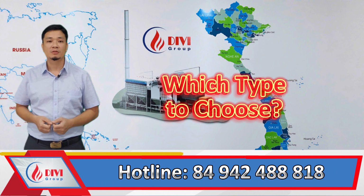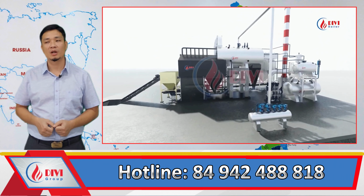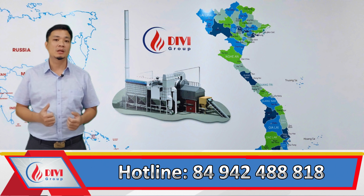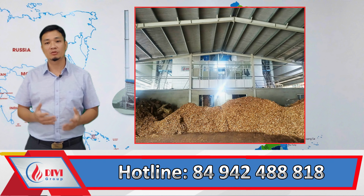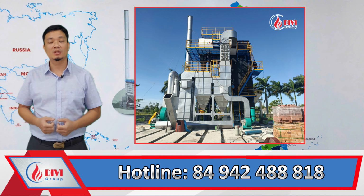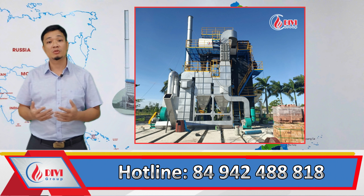When to choose which? If there are no specific site constraints, the CFB design is generally preferred. However, if the project is limited by floor space and the boiler capacity is under 50 tons, then the BFB design is a practical and space-saving choice. For instance, DIVI designed BFB boilers for TH Milk, 2 8-ton units, and Tuan Gan Oil Factory in Vinh, 1 5-ton unit, both optimized for limited space and running efficiently on chipped wood fuel.